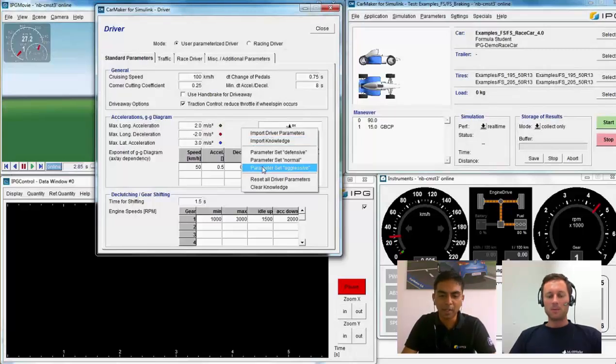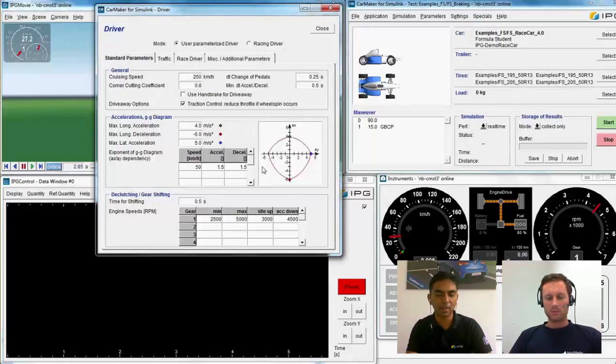Unlike if I select the parameter as aggressive, then this is typically a person who is taking the car to its limit, which means driving at high speeds, at higher acceleration in both longitudinal and lateral direction. Well, so at the end, we can say it's a controller, yeah, but a very sophisticated parameter set. Spot on. And you also see there is an option to configure the gear shift.